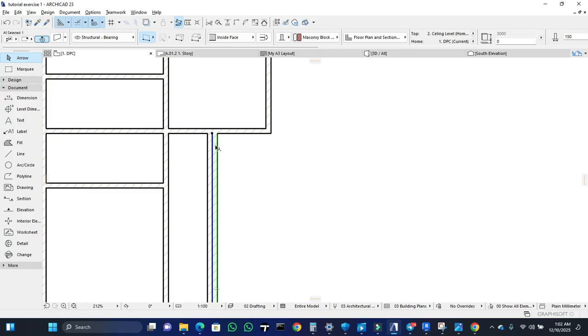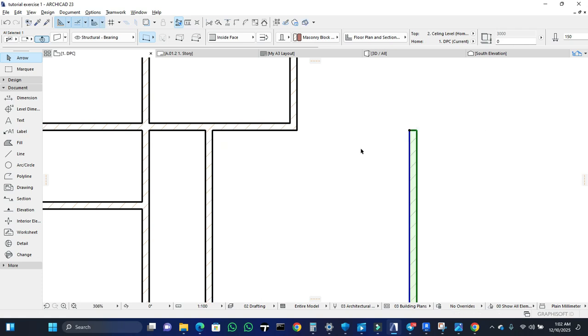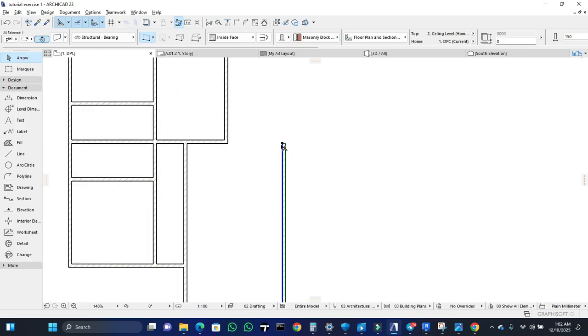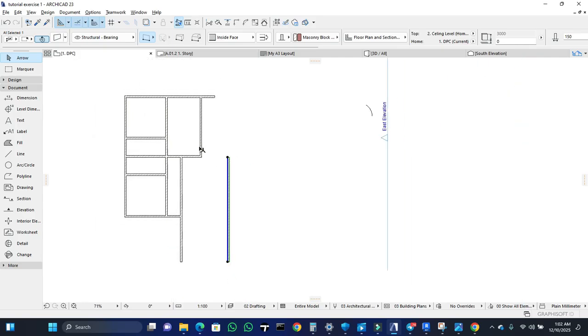So I'm mirroring a copy directly at that point, and I'll drag that new copy 4.2 meters from the original point. So Control D, drag it, type 4.2. I click on it and type 4.2 and it establishes at the new position. Then I'm good. Alright, so that is it. And then let's look for where we will have our dining and this.